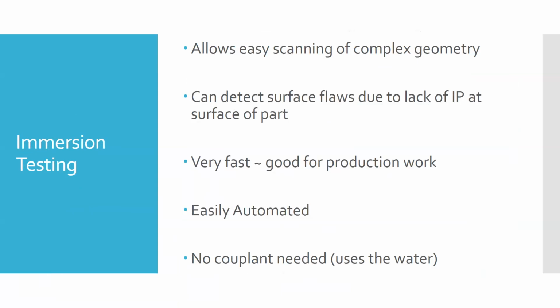The downside is if you're using water, what's the downside to using water? What's water inherently cause problems with? Corrosion, right? They typically use pure water. They use like a DI water or something like that, deionized water, so that it's less likely to cause corrosion. It's the ions in the water that cause the corrosion issues. So if you have water where those have been removed, it's not as big of an issue. You just got to make sure you dry the part. But again, if you have a part that's got nooks, crannies, crevices, that kind of thing, there may be some challenges to making sure you fully dry it when you're done.